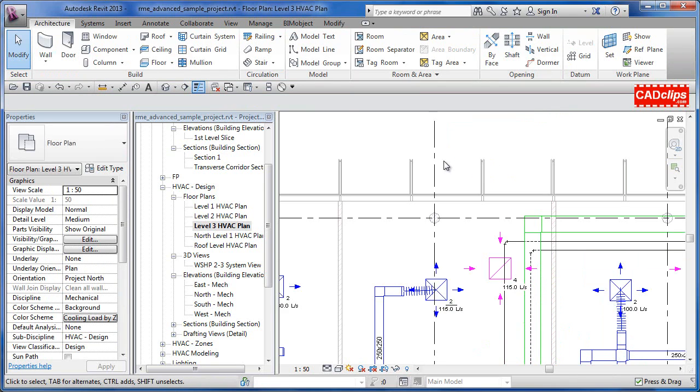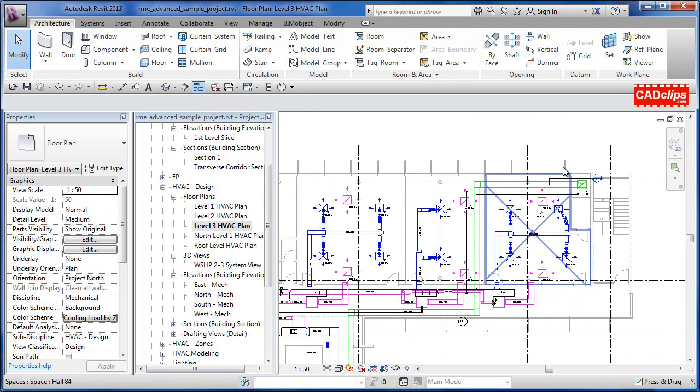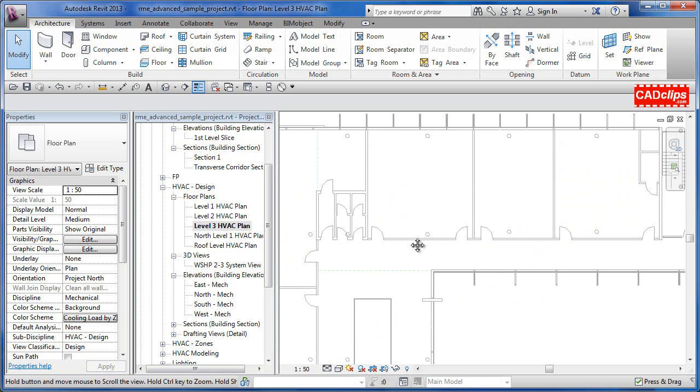So really nice feature. You can place the grid lines in early and then literally grab all the grid lines and say put this column in all those locations, and go back and fine tune it from there. So it's very good to have our grid lines in, and then we dimension them, and then we can turn the little grid bubble on or off at the ends of each grid line.